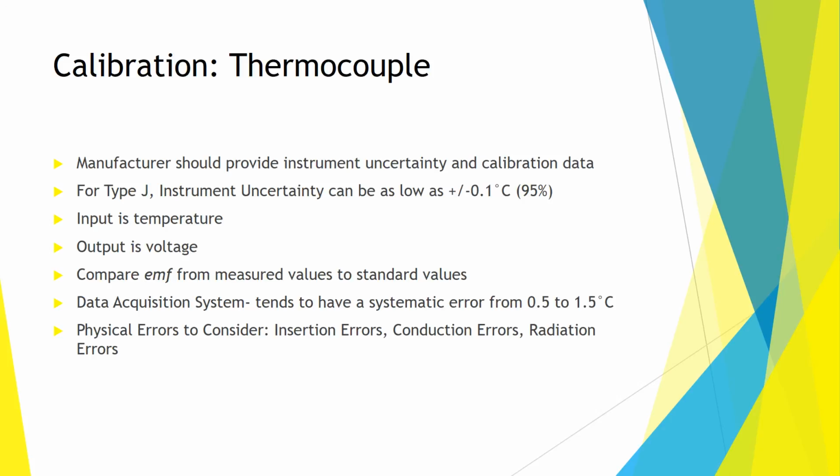When the thermocouple probe is inserted into the calorimeter, there is a risk of conduction taking place between the water and the surroundings. This would be reduced with proper insulation. A radiation error can occur based off of the fact alone that this is a solar calorimeter, and the radiation from the sun could affect the thermocouple if there is exposure to the probe. This can be minimized, however, if radiating shields are used to reduce the probe's exposure to the sun.